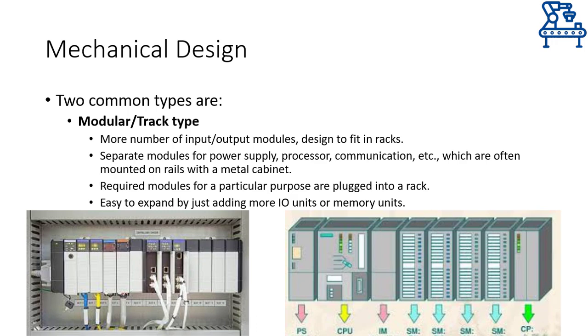Typically, different kinds of input, output, and memory modules are added to expand the PLC. However, it depends on the power supply module and the processor module what is the maximum number of I/O and memory modules that can be attached. Normally, to limit the number of modules that may be attached with the processor and the power supply, the rack is designed with that many slots only. So the rack limits the number of modules that may be attached.